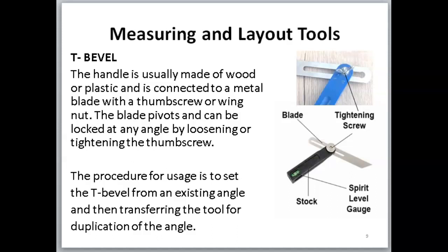The procedure for usage is to set the T-bevel from an existing angle, such as from a protractor, etc., and then transfer the tool for duplication of the angle onto a wooden surface.